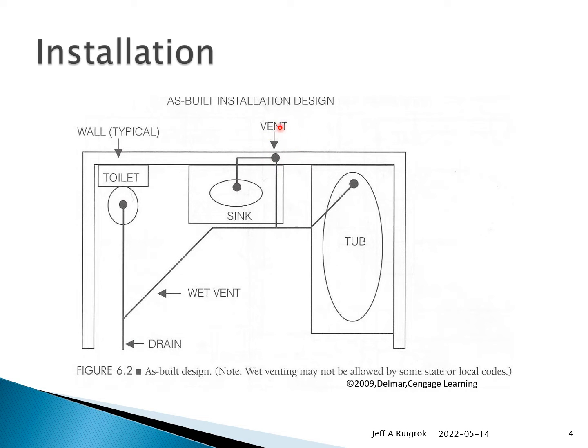So there's only a single air pipe that supplies air to all three fixtures. It does change some sizing, which I'm not going to get into, but this would be something you actually want to build. The other drain had piping coming up in this wall, a ton of it. This one just has a single one. Anyway, so it's much simpler.